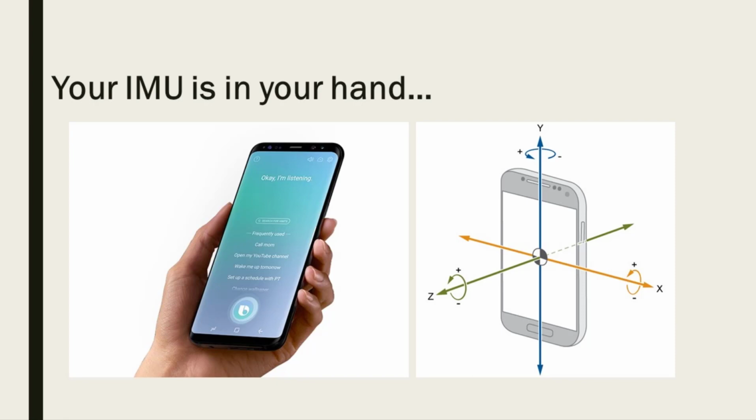So okay, you can see that we have selected our phone as IMU, and now we're going to implement our model and simulation and files in Simulink, and then we deploy it to the Android device. And by the way, you can do this tutorial on iOS devices as well. You just need to change the sensor inputs from Android to iOS. But as I told you in the last tutorial, I don't have access to Apple Developer ID, so I can't do that right now. So it's up to you, but it shouldn't be hard, just changing the blocks.